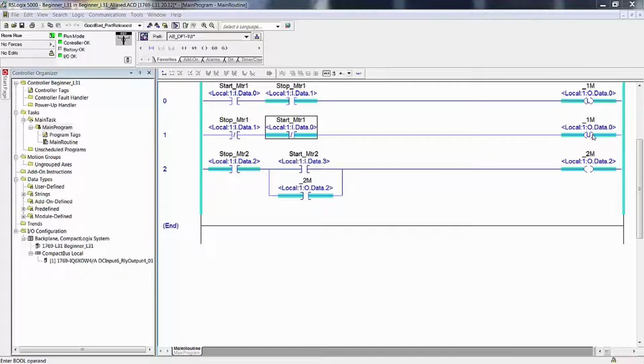Electrically, you have two coils. Here you only have one, but if this were an electrical circuit, this would be a stop push button, a start push button. Now that would be normally closed if this was an actual push button electrical circuit. So as long as you're not pushing it, normally closed, it's closed and you have continuity. When you push this button, the normally open closes, energizing this coil. This contact right here is part of that coil.